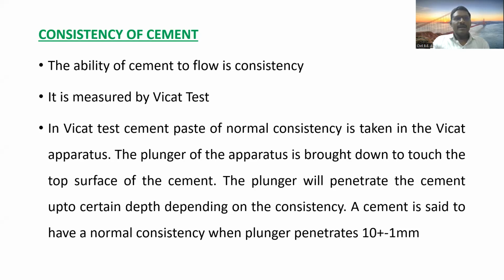We can measure that consistency by the Vicat apparatus, that you have done the practical on also. In the Vicat apparatus, cement paste of normal consistency is taken, and the plunger of the apparatus is brought down to touch the top surface of the cement paste, and the plunger will penetrate the paste up to a certain depth, depending on the consistency.